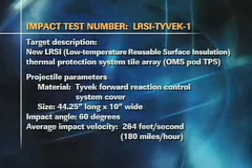forward reaction control system thrusters. These thrusters are located near the nose, in the nose of the orbiter. There was a concern that the butcher paper material that was being used for those forward reaction control thrusters had the potential to damage windows and damage tiles around the windows. Some testing was conducted with the butcher paper, and this Tyvek cover was recommended as a design change.